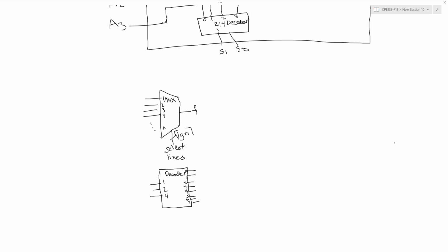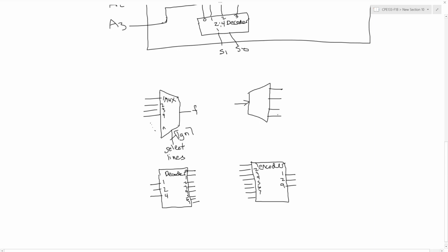Now these two components have many uses, and we'll see that they come up many times in different types of designs. Sometimes also we might see related blocks. So with the decoder, I could also have an encoder block, which essentially does the opposite of the decoder, takes multiple inputs, where only one of these is exactly 1, and encodes the address of the input line on the output. And the demux, which takes an input and based on the select lines connects the input to that corresponding output.